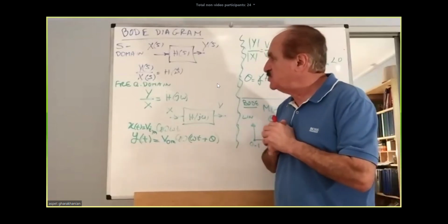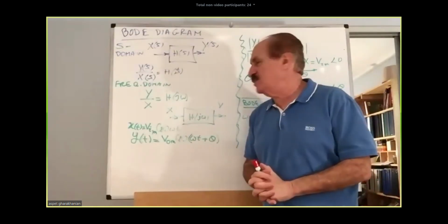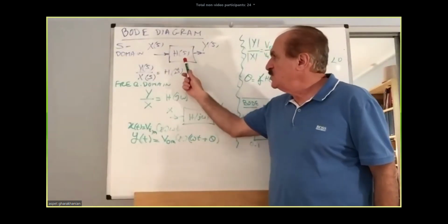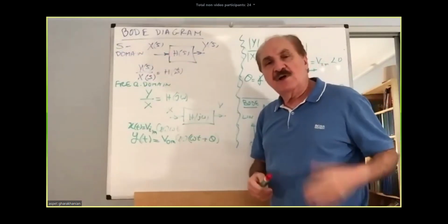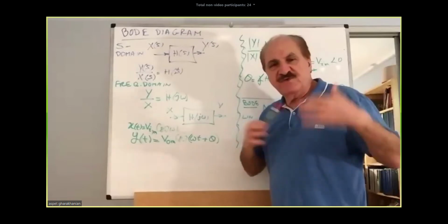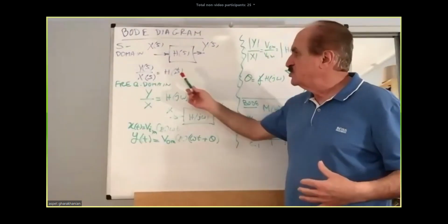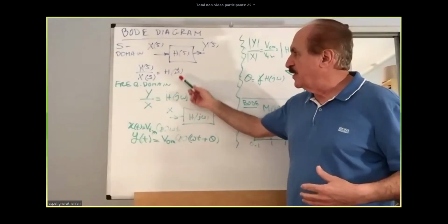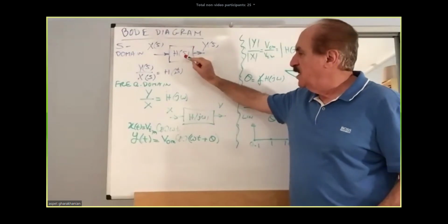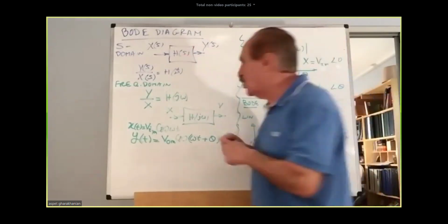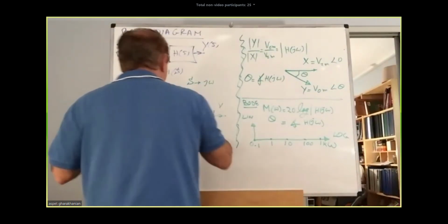So let's see what is the frequency transfer function in the first place. Once you find the transfer function of a system in the S domain, all it takes to convert it into a frequency transfer function would be to substitute s equal to j omega in the original transfer function. So s will be substituted by j omega. What it does,